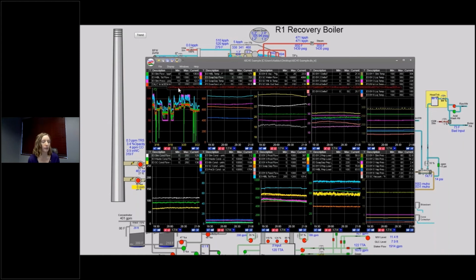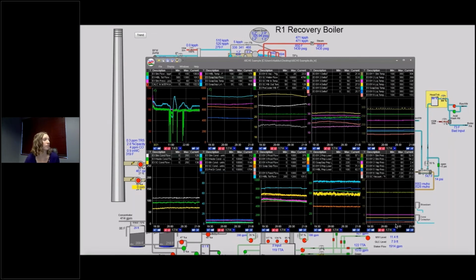I'm going to go ahead and clean up some of the other tags just to reduce some noise there. And now we see basically we could use this tag in place of the green one if we ever have those meter failures, because this will be a pretty good prediction of what that tag should be. So yeah, that's an example of using Park Model or a similar advanced analytics tool to do some real process improvement.